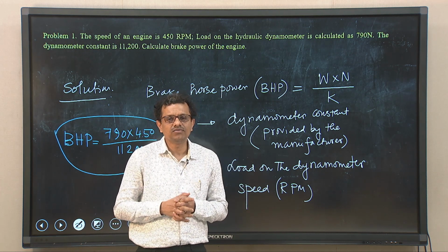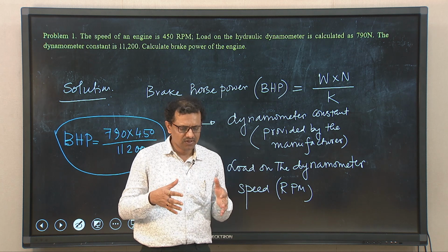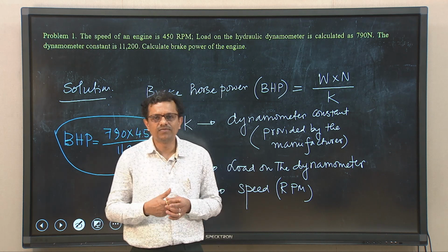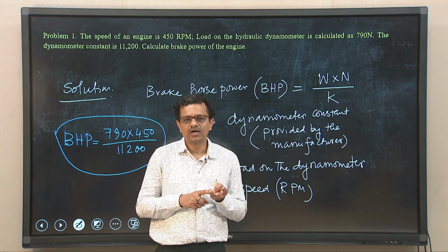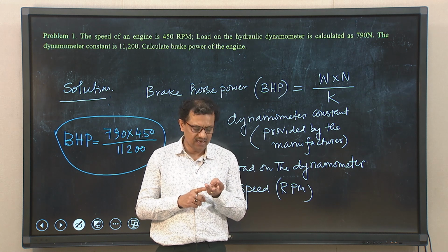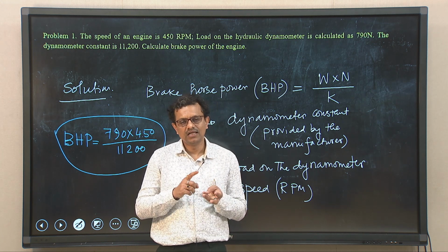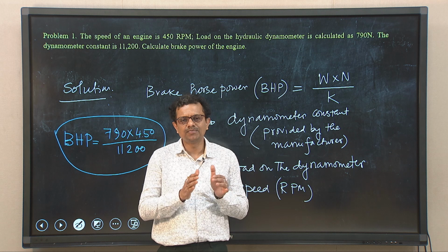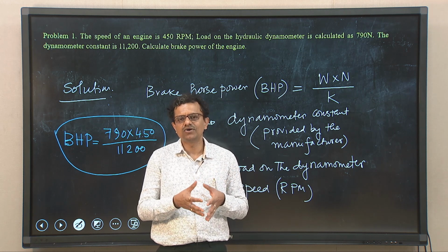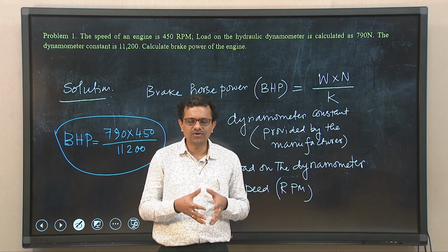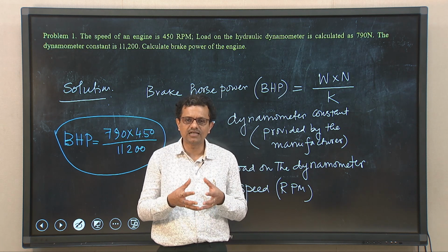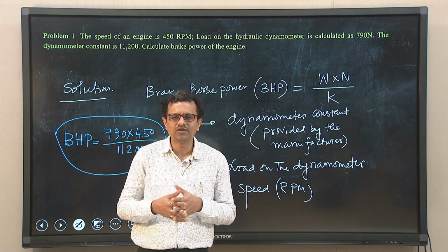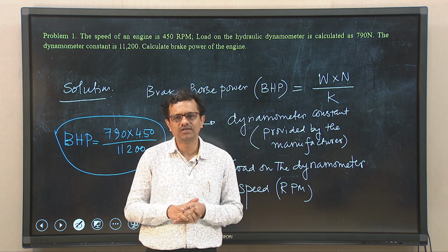If we recall what we have discussed in a few previous classes in the context of engine performance, we have discussed the measurement of a few important quantities like speed, air flow rate, fuel flow rate, indicated work, and today brake horsepower. Indicated power, the power available inside the cylinder, is certainly not available at the engine shaft. So, today we discussed brake horsepower measurement, which is the power really obtained from the engine. The measurement of these important quantities has been discussed in a few lectures.